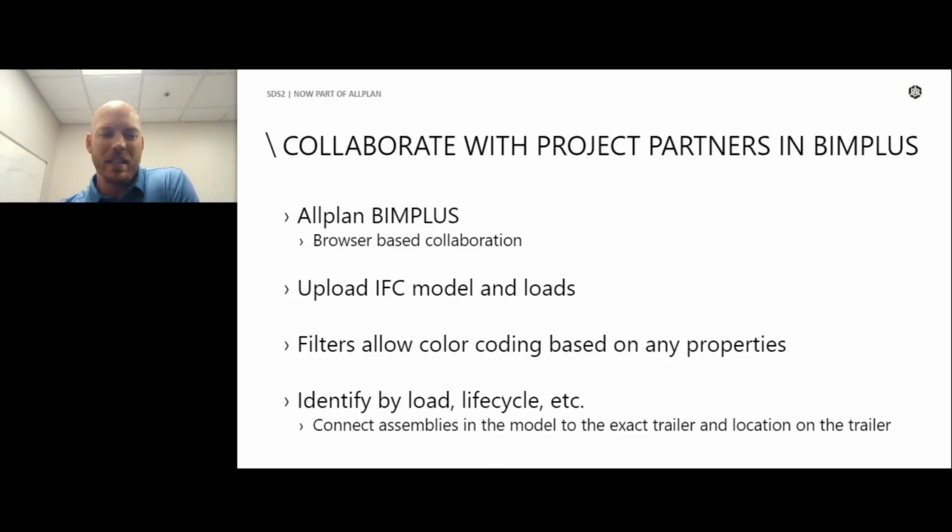Really, the idea is, similar to the way that I color coded the SDS2 model, we'd be able to upload our IFC files to our online collaboration platform. Any of our project partners can be invited to that. It's just browser based, so they don't have to have anything additional installed to view that. And then what you can do is set up a filter so it color codes the piece in the structure to the piece in the trailer, the exact same color, and then we can connect the dots of, okay, this piece in this structure showed up on this trailer. It's very, very slick.